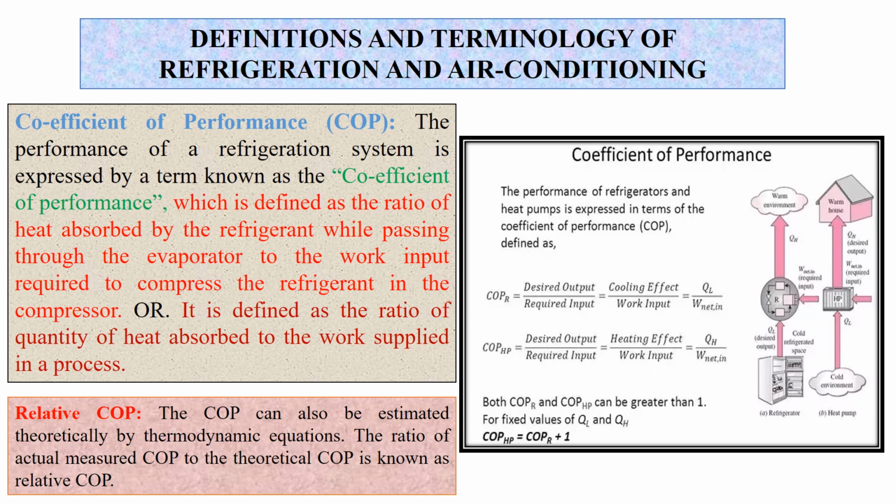Okay, what is the COP? Very simple: the amount of heat absorbed by the refrigerant while passing through the evaporator, to the work input, or work supplied. It is very simple, the amount of heat absorbed to work supplied, that is the COP. COP is always greater than 1 for a conventional system.